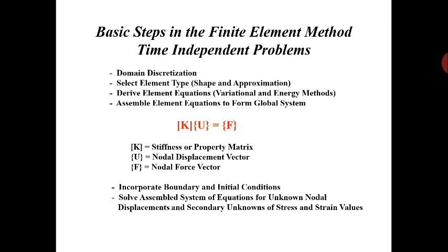so that we can have the multiplication factor to the stiffness matrix, that is equal to 0. So we can eliminate that particular row and column throughout the matrix, or we can say throughout the equation, and we can have the easiest solution with the help of the uneliminated rows and columns.